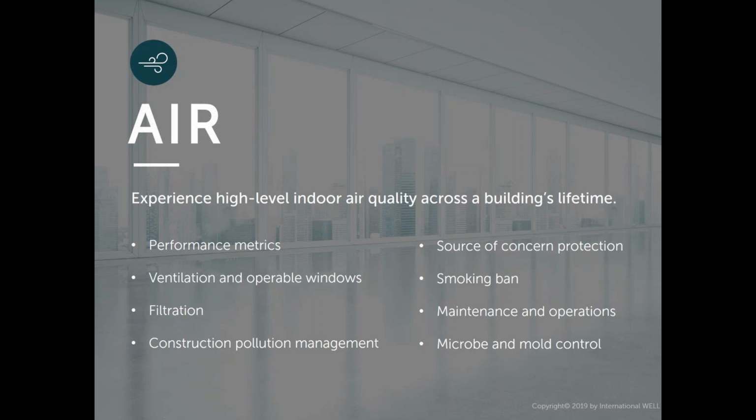There are design requirements to protect the health of the actual workers on site, but then there are other things you would want in every building, but particularly a lab where, depending on the type of lab, there's sensitive equipment and different hygrothermal, so heat, air, and moisture conditions in that space that you need to maintain. And part of the construction pollution management is things like material protection and cleaning to ensure you're not introducing any unwanted contaminants into the space, and also to ensure that the materials aren't absorbing unwanted moisture, and then installing those into a space where you could then get diffusion.